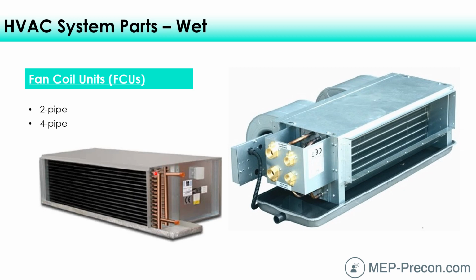And so this could maybe be a means of cost savings because, as you can imagine, this is going to have half the pipe in a system as this would. And piping is a lot to coordinate, a lot to insulate, a lot of money to fit above the ceiling and coordinate with all the other trades and so forth. I'm not saying if it's good or bad, but it's definitely a money saving idea to have a 2-pipe fan coil.